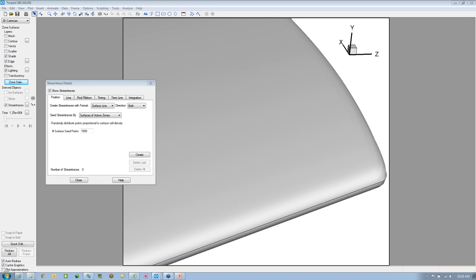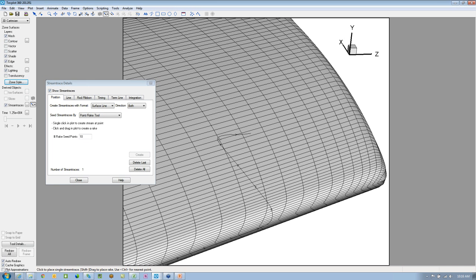Okay, nice. Hey, can you release one stream trace directly on a node or cell center? The answer is sure. And the way that you do that when you're doing stream traces and you do the point, if you hold Control, it will actually select the nearest point as a launch. So you can think of it as it will grab a node. If I turned on the mesh, you can kind of get a sense of it. So when you hold Control in Tecplot, it actually will snap you to a node. And we'll use that node as a launch point.